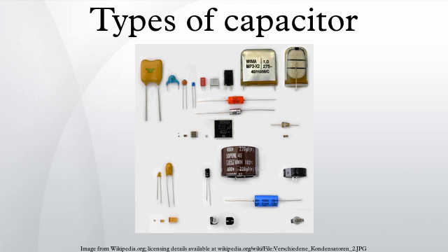In electrolytic capacitors, the insulation resistance is defined as leakage current. For electrolytic capacitors, the insulation resistance of the dielectric is termed leakage current. This DC current is represented by the resistor Rleak in parallel with the capacitor in the series equivalent circuit of electrolytic capacitors. This resistance between the terminals of a capacitor is also finite.